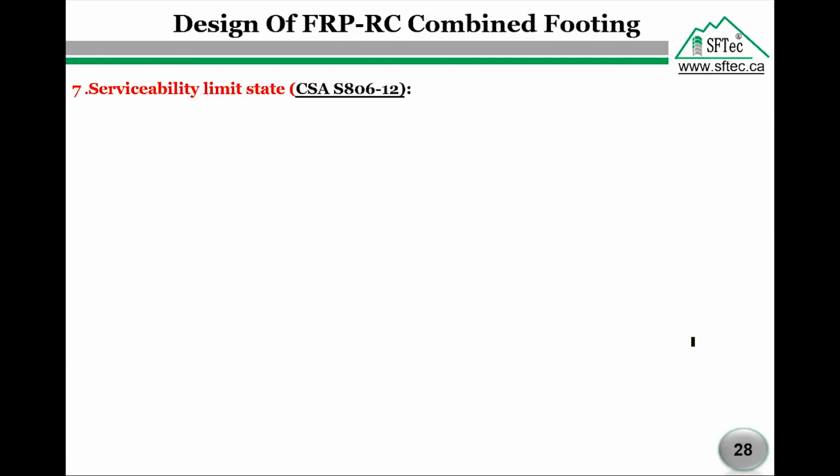As I mentioned in the previous webinars, in order to have a successful design for any structural element with FRP bars, you should check the serviceability limit state. So we will apply these checks on our retaining wall. The first one is to check the maximum stress and strain in the FRP bar under full service load.